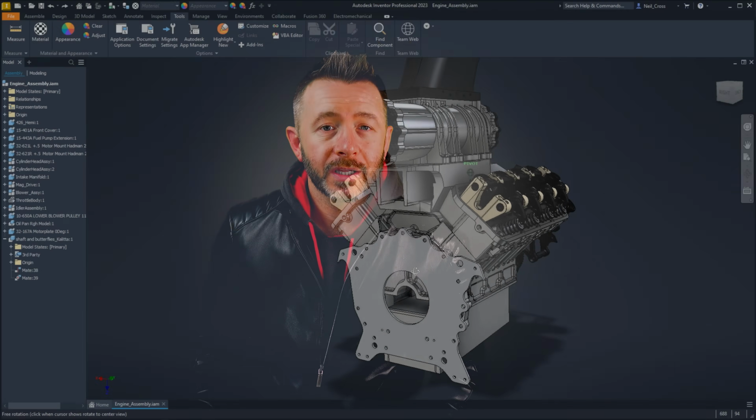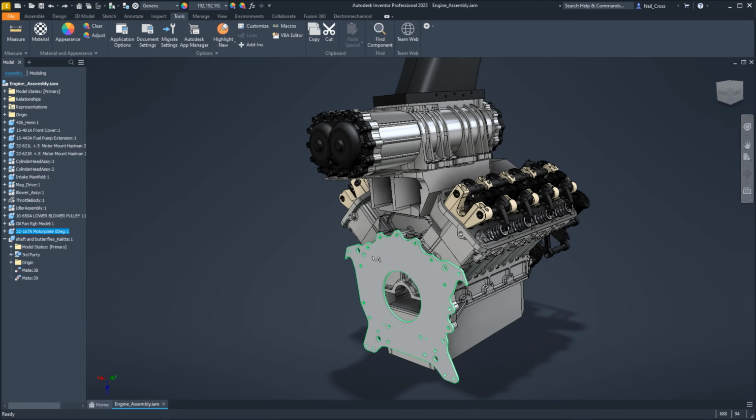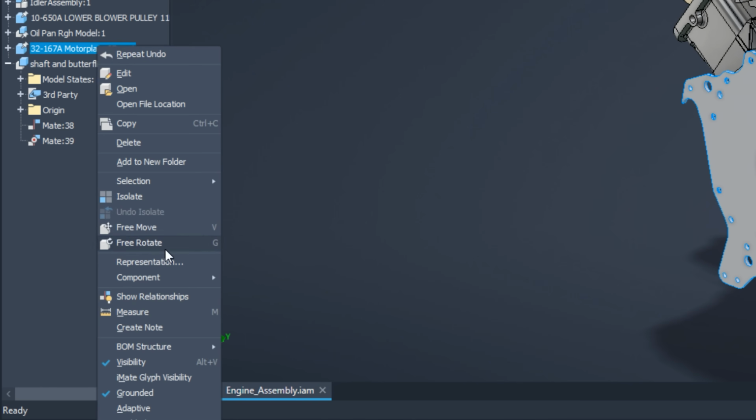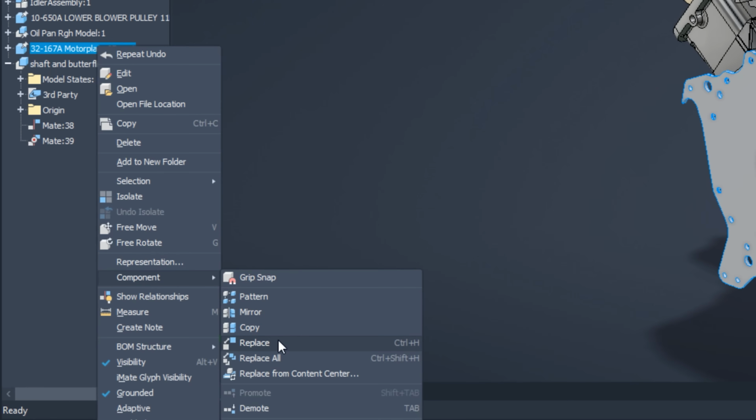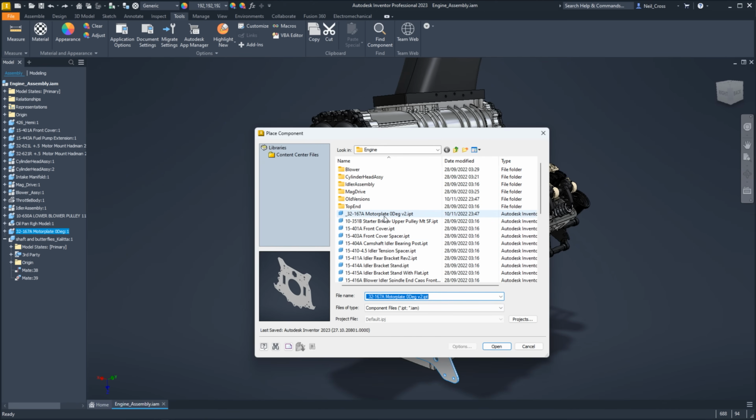But again, that was 4 years ago. But over and above that, Inventor obviously runs rings around Fusion when it comes to the construction of not just large, but also just the handling of smaller assembly datasets. It offers a wider array of management tools like assembly component replace. So if you've got a part that you want to just quickly swap out in your assembly with another part that you've got, it might be the same part or a completely different one, Inventor will use component replace. It'll go grab another part and just switch them over.